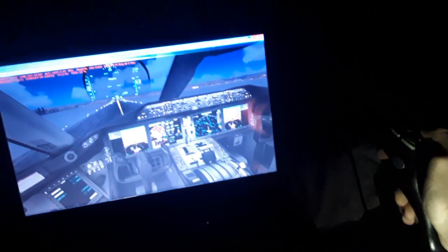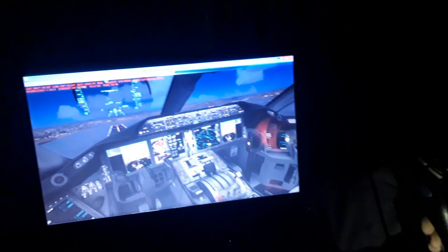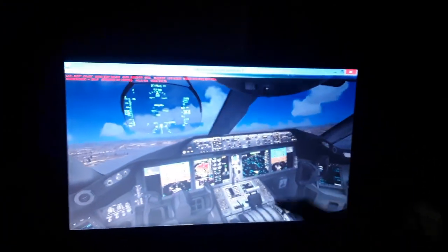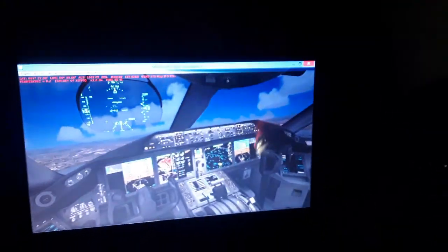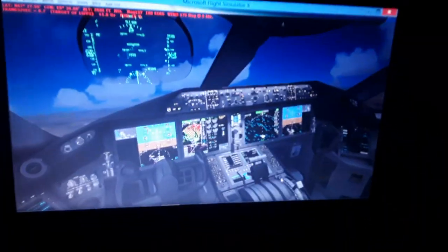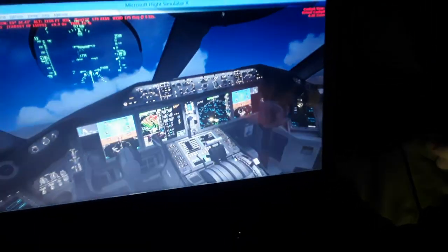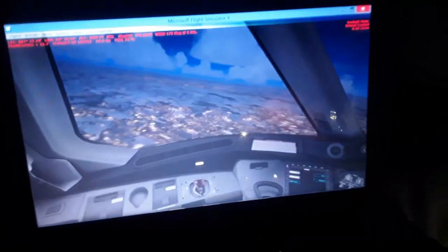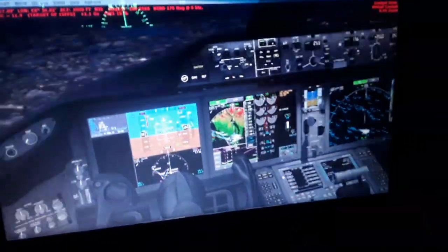We start the rotation, less than 9 degrees of pitch attitude for rotation, a pitch trim a little bit. So we have the initial climb, landing gear up. So we keep climbing. So we climb over here, as you can see. You can see the indications that we follow.